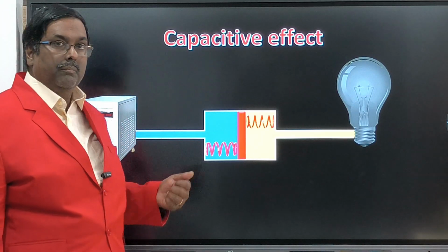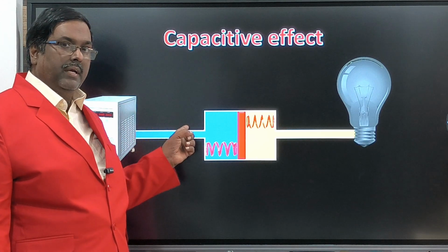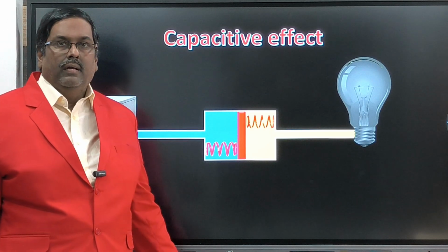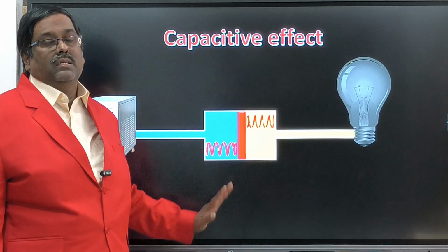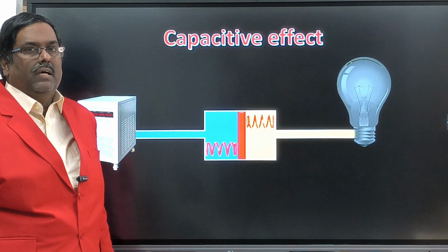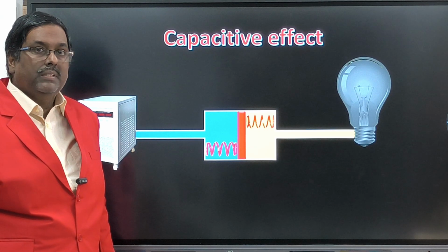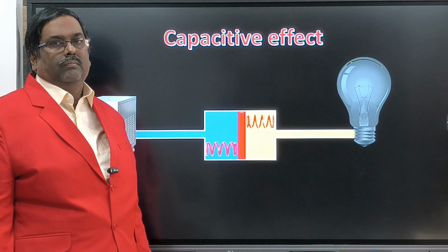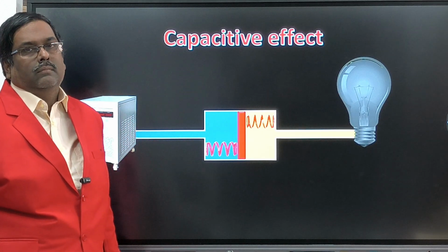This is very, very important, basic. If you don't understand, watch my video again from the beginning, so you will get it. Because if there is any confusion in this understanding, I am telling you, up to the end you will always have confusion. You will think the capacitor is like a battery, storing energy and releasing energy whenever required. That is also a purpose, but in an AC circuit that is not the purpose. That is only for the DC circuit. Okay. In an AC circuit, the capacitor acts for a different purpose.